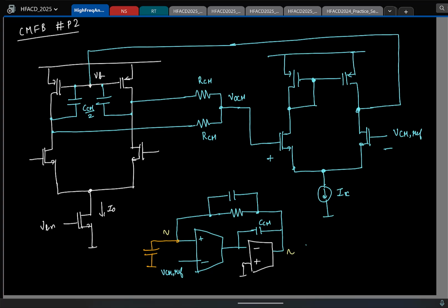Fine. Please recollect, we discussed this while discussing the two-stage Miller compensated op amp also. So you can put an additional capacitor. I'll call it CMZ to denote it is for the zero. So now anytime you see a change at the output, this capacitive path will be active. This capacitor will provide the faster path and make sure that we have a capacitive division, so things get fed back instantly, right? Otherwise you will have a delay through this RC. Okay. So that capacitor also we can add.